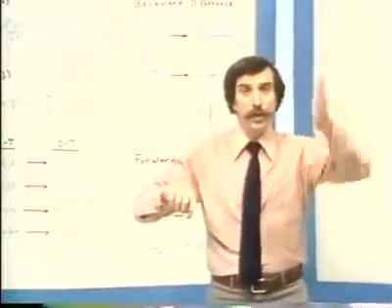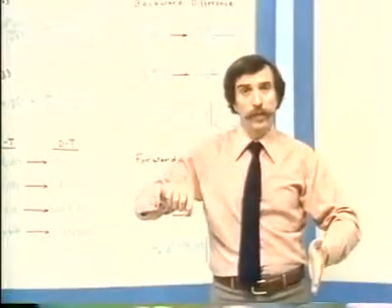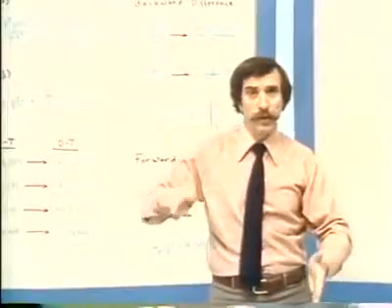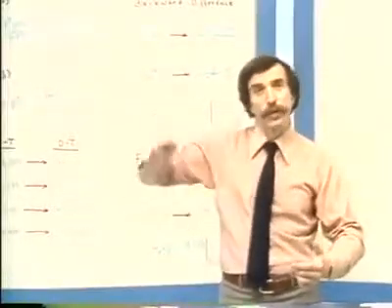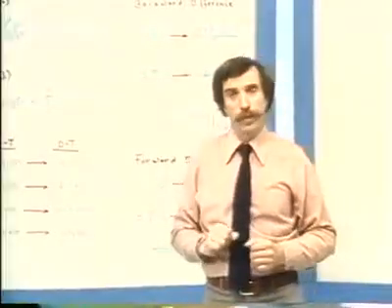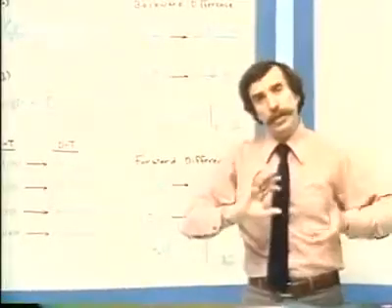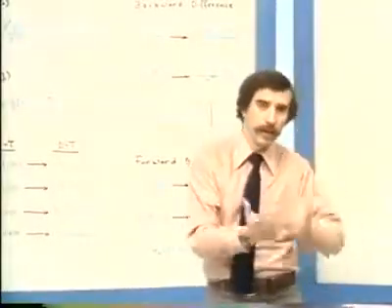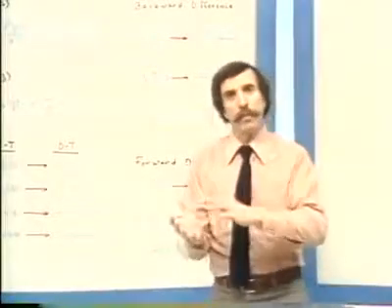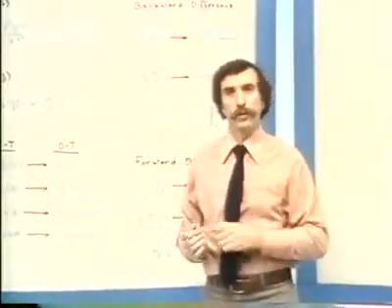Because it's this over here that represents the frequency response in continuous time, and this contour over here that represents the frequency response in discrete time. So that's an important property. We want the j omega axis to map to the unit circle.